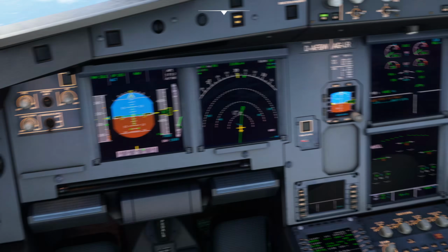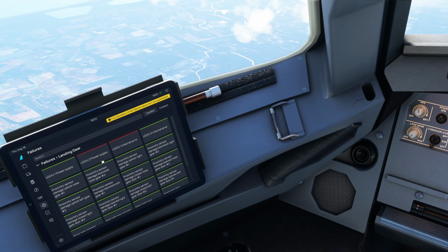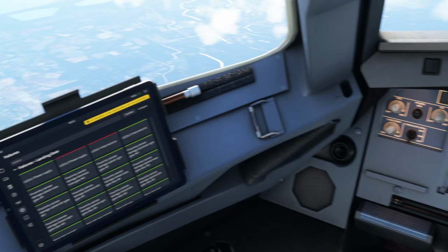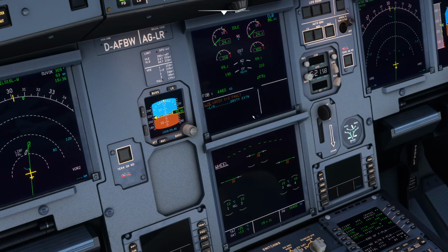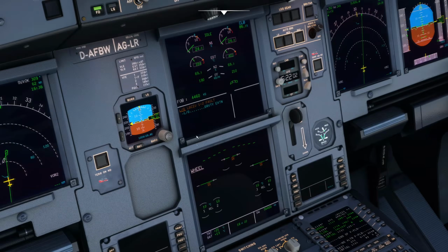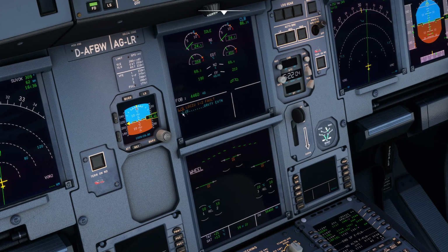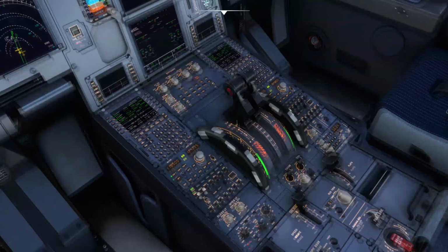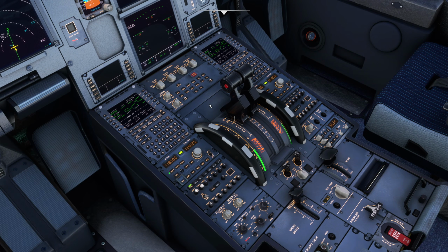But here we are. I've now given us 2 faults. We've lost power to LGCIU 2 and LGCIU 1 has an internal error. So this gives us the more concerning warning. And here, of course, I already had that switched off. But there it is, landing gear LGCIU 1 plus 2 fault, landing gear gravity extension. So that's leading us to a QRH procedure that we have to follow. It's very straightforward and it gives us the instructions on using that control. But like I say, there is another fault that would get us here, which would be a dual hydraulic fault, which is a very complex failure, but we won't go into that today.